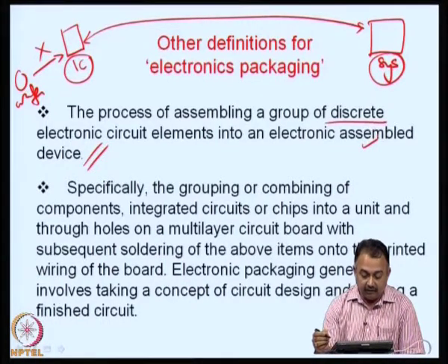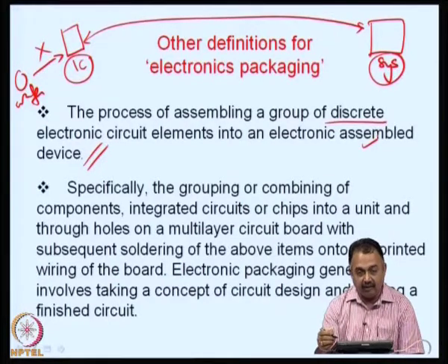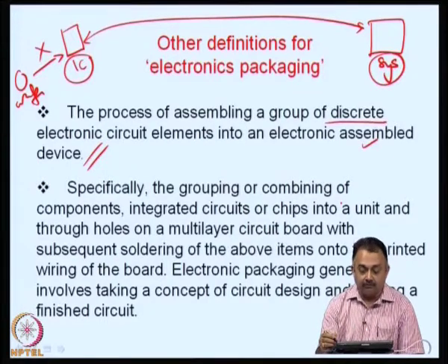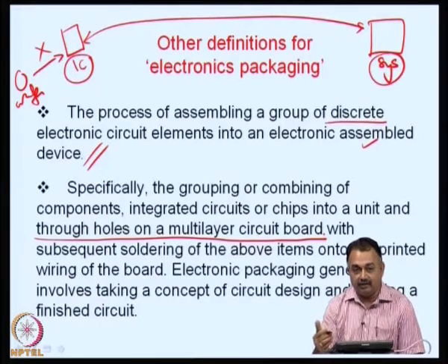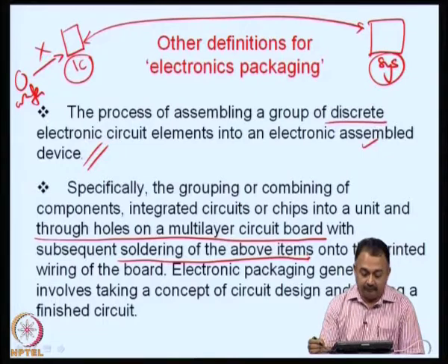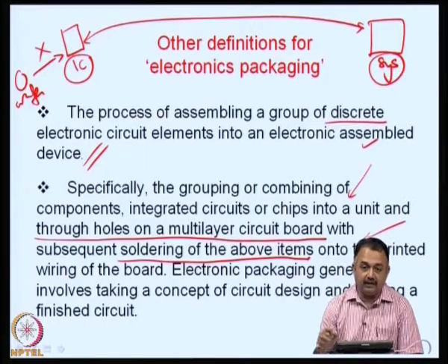The other definition that I have brought here is specifically the grouping or combination of components, which include integrated circuits or chips, into a unit and through holes on a multi-layer circuit board. This talks about second level packaging or board level packaging. We will see that later, with subsequent attachment of the above items onto the printed wiring board. So, here we talk about packaged devices, and about second level packaging on which the packaged devices are mounted, and finally,